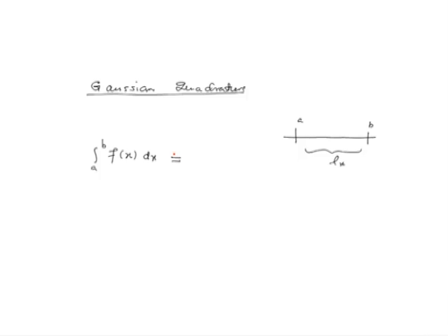Now, you can verify that this is given by Lx by 2 if we map it to an isoparametric element with the extent -1 to 1, so x and the natural coordinate xi which ranges from -1 to 1.